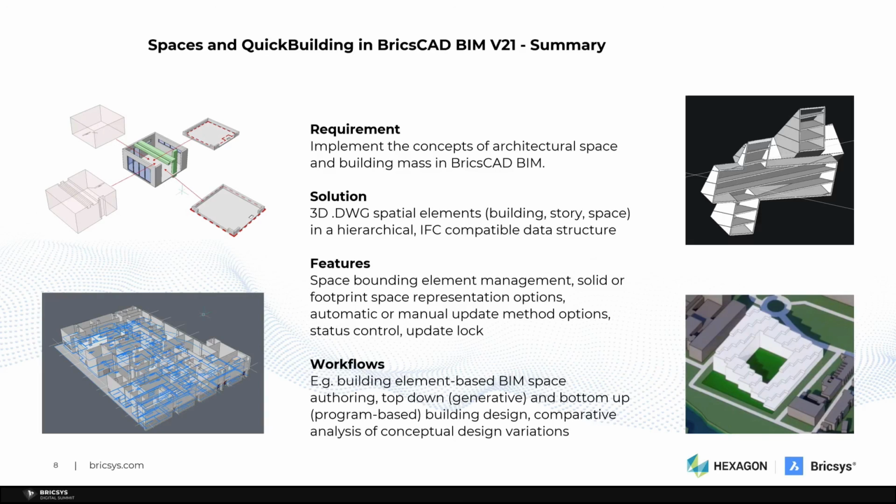For example, the building element based BIMSpace authoring, where we automatically just place the spaces based on their bounding elements. We saw how spatial elements can be freely modeled to achieve virtually any geometry while still maintaining connection with their bounding elements. We saw several examples of how to generate building designs top-down or bottom-up based on an architectural design program.